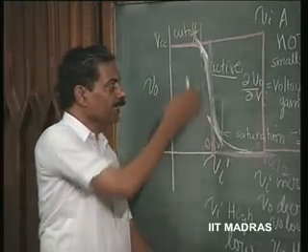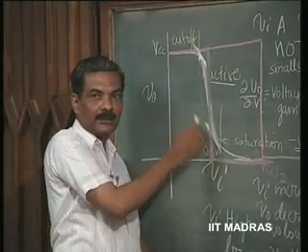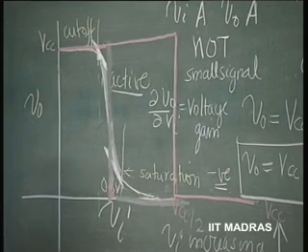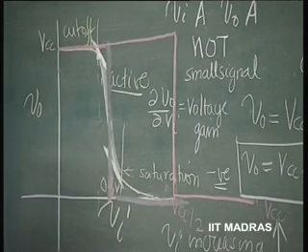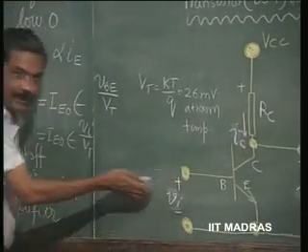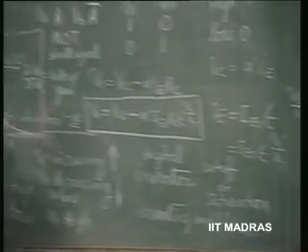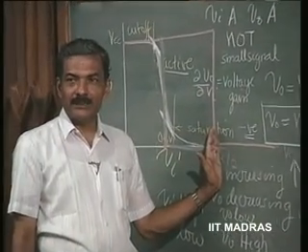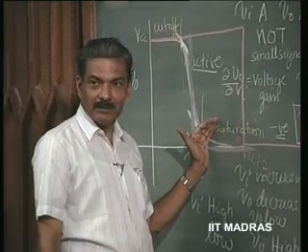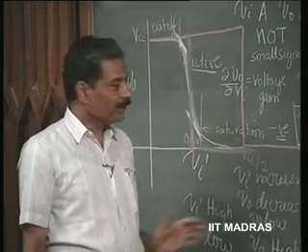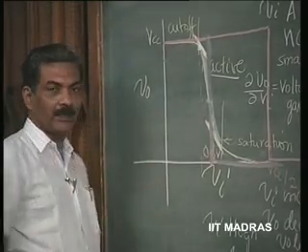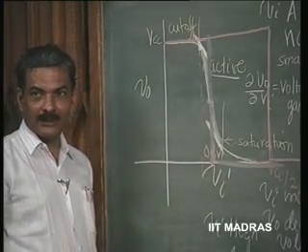In practice, you can compare it with the bipolar junction transistor inverter, where the transitions take place at 0.6. This can be shifted suitably by adding additional diodes in series with this. So, you can just put additional diodes and shift the transition to maybe even at a point equal to VCC by 2, but the transition's character remains similar to this, exactly like this. It is not abrupt.